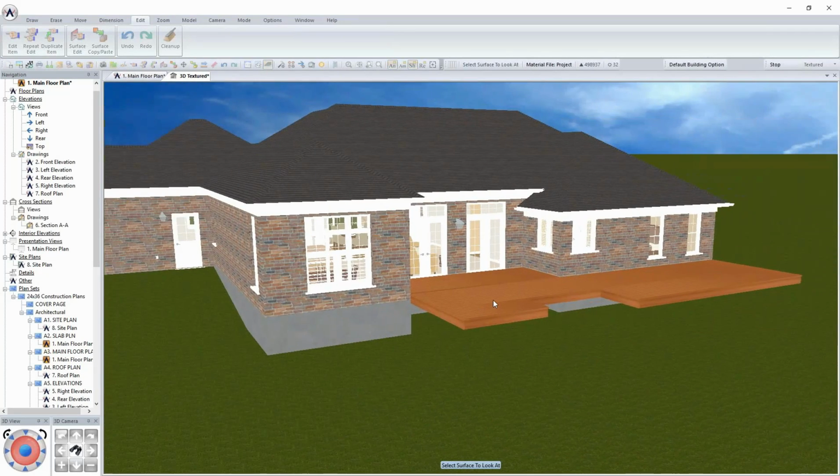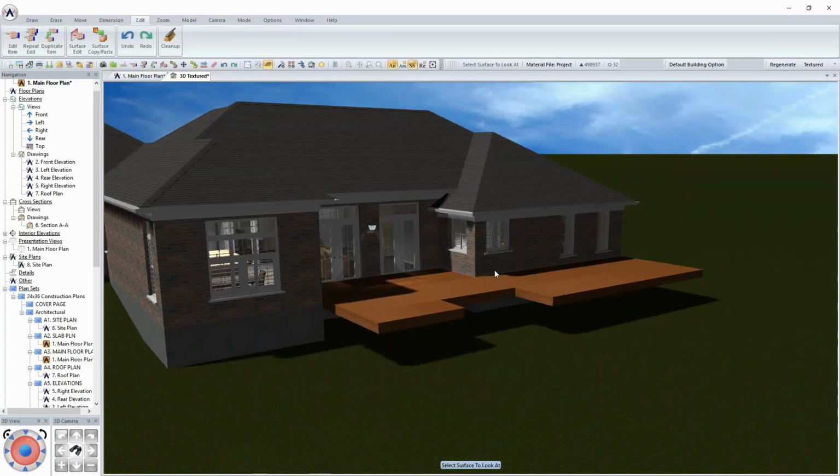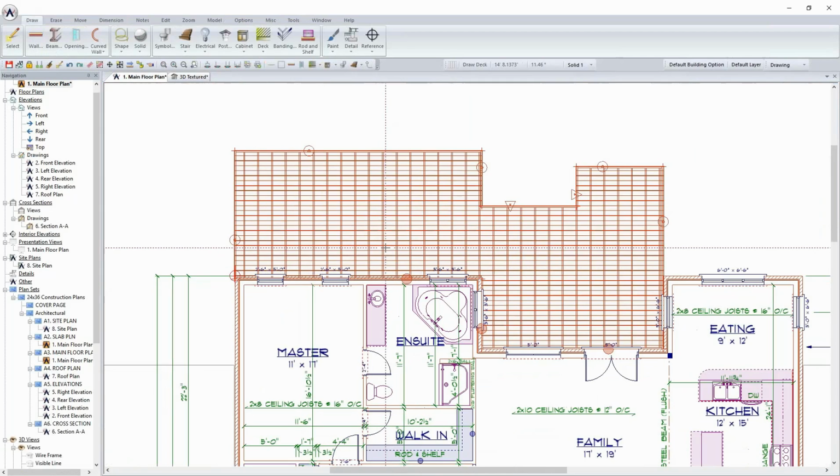But as I just kind of pan around and take a look at what I'm doing, the top of the deck surface is going to find where the floor system is. It's going to run that across correctly for me. When you take a look at the deck, as you place it, it's going to place reference circles on each side of the polygon. This allows you to then adjust that reference circle, if necessary, to find a material that you're attempting to snap it to.